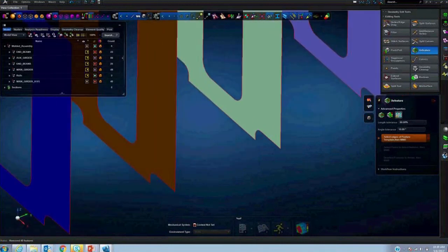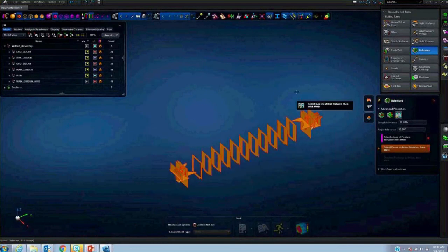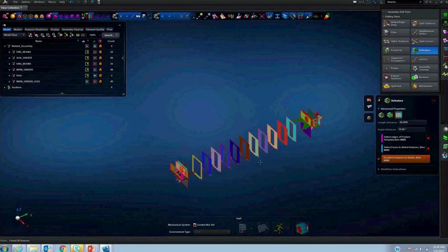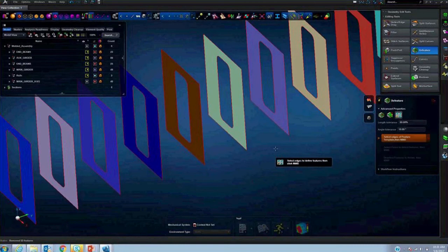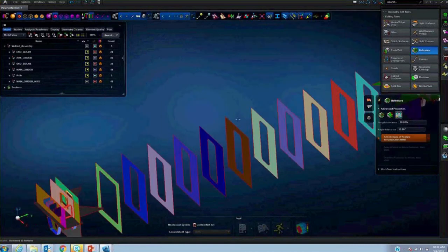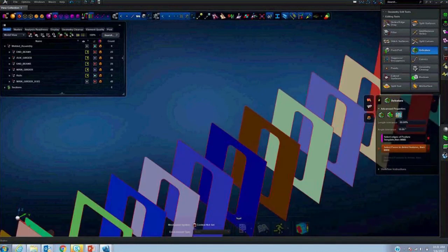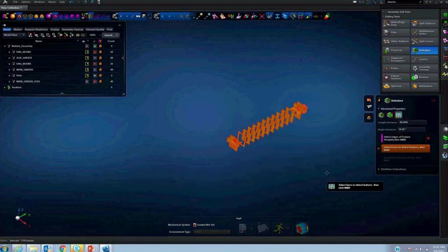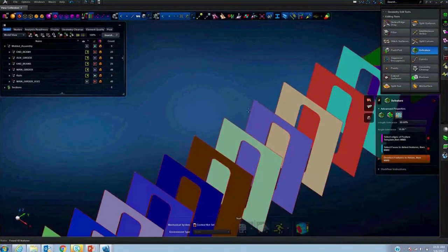Let's take a look at this feature in this corner and recognize it by the pattern. Now select the entire model to see how many of such patterns there are. And it did identify about 26 of such features, and we defeature them. Likewise, we can also look at the traditional fillets in this model. For example, it is a small fillet. Identify one of them, select the entire model, and see how many are there. And there are 42 such features.